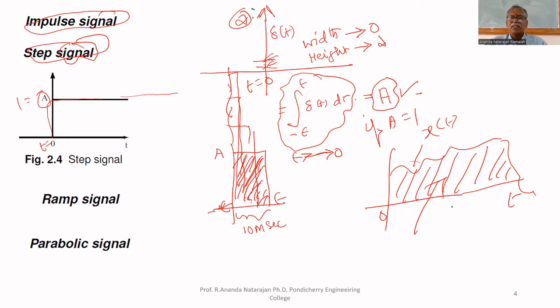If we take the Laplace transform of this, the Laplace transform of del of t equals 1. For an impulse whose magnitude is A, the Laplace transform will be A. For a unit impulse input, its value is 1, so the Laplace transform of del of t equals 1.